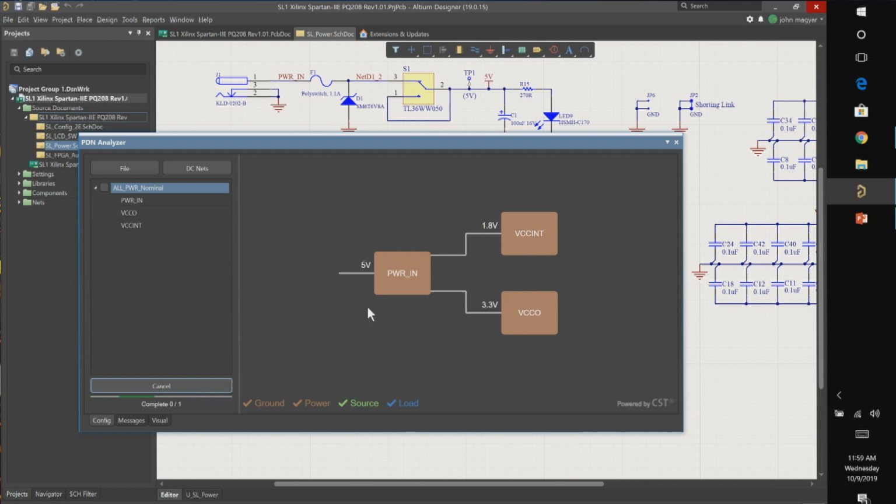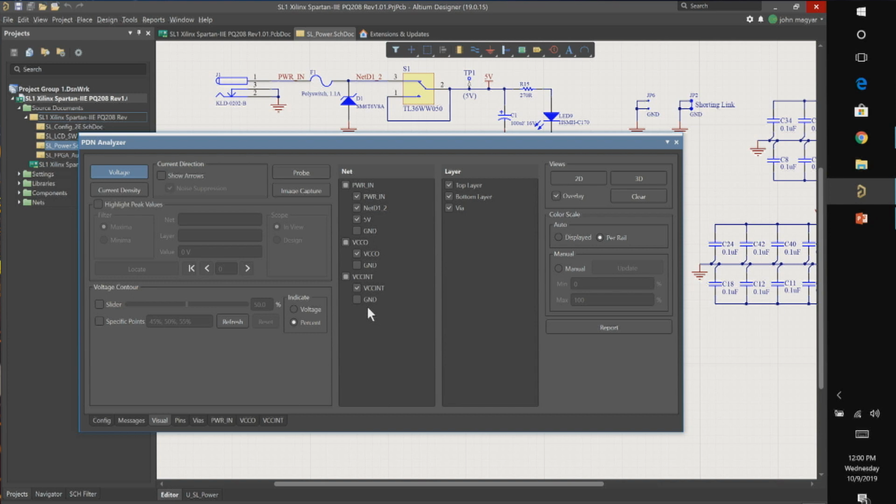What this will do is look at all of the copper and extract that out, and does that using its ODB++ format, all transparent to the user, so you don't have to worry about generating that output. It's doing that in the background, so it gets that accurate physical description of every layer. So all of your planes, polygons, and routing. It'll reconstruct that copper and then pass that to a static engine. In this case, it's produced by a third party called CST. That's all they do, are simulation tools and analysis tools, and we simply access their technology and put the interface around this so that you can harness that capability.